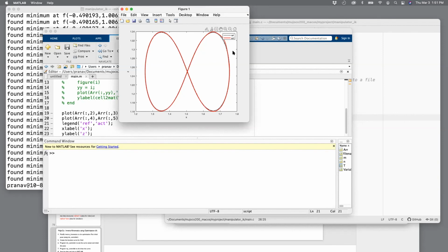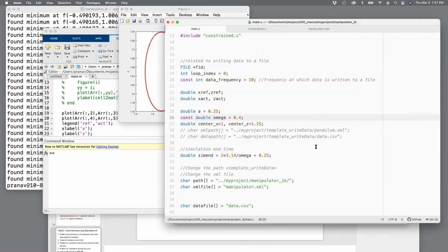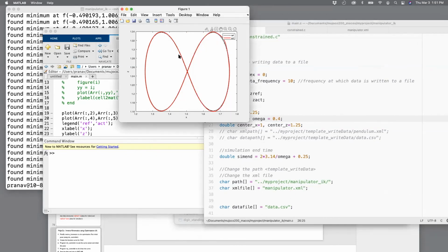It's got a speed component to it, which the PD controller cannot quite damp out. So if you increase the damping, perhaps you'll get better results. So increase the damping, increase the gains P and D for the individual joints, and then you can maybe get it to go much faster and plot the lemniscate.